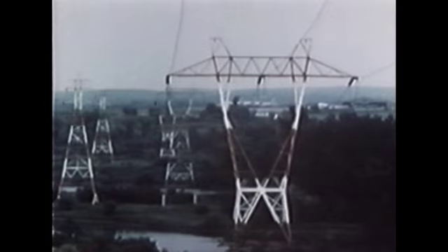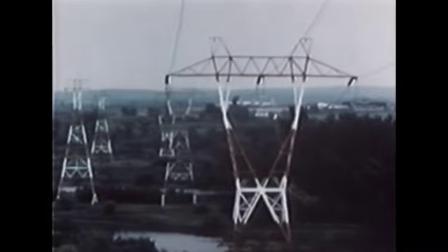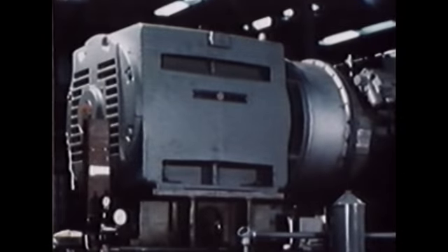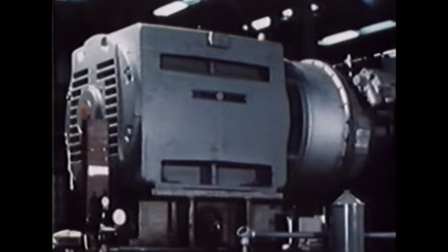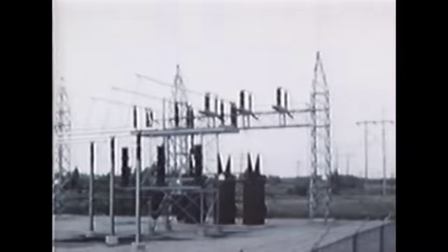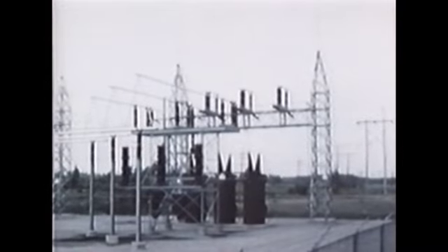3-phase generators are popular because they make more efficient use of the generator's iron core and its copper windings than do single-phase generators. 3-phase current can be distributed more efficiently than single-phase current. And large 3-phase motors run better and are less expensive than single-phase motors. In addition, a major reason alternating current is used over direct current in electric power systems is that it can be transformed easily to different voltage levels.